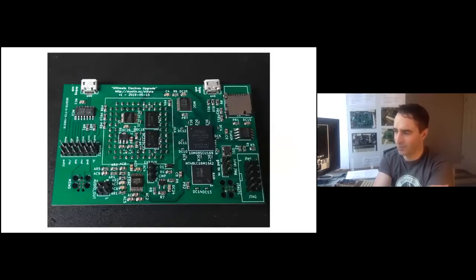Here it is with all the hand soldering done for all the through-hole components. Lots and lots of pins to poke down into the ULA socket, and then a bunch to come up. There's the JTAG connector, so I can program the FPGA, in the bottom right here. On the left, connectors for the debug microcontroller.